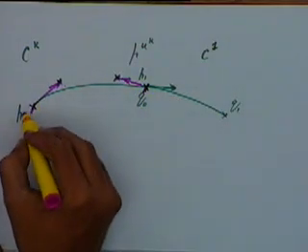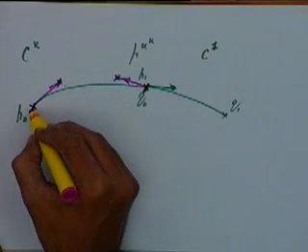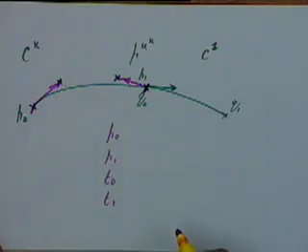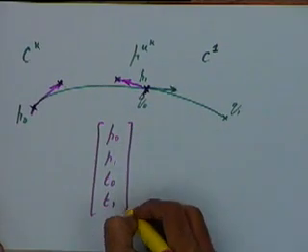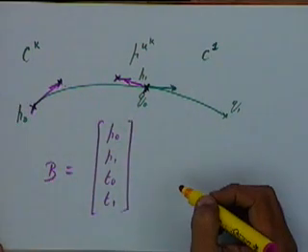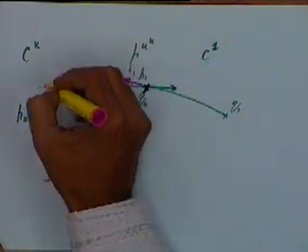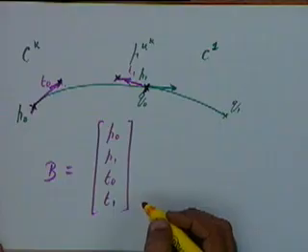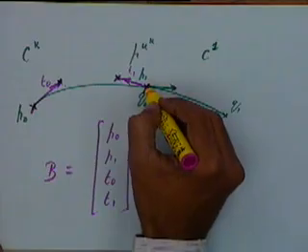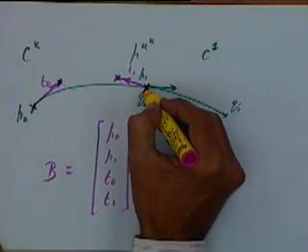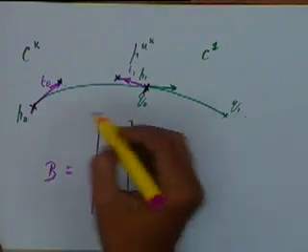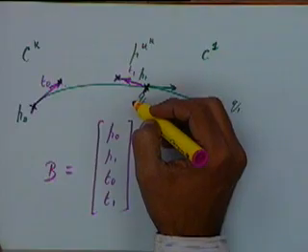If I consider the geometric form of this curve, that will consist of P0, P1, T0 and T1. This is the definition for this first curve, the B matrix for the first curve. This vector is T1, this vector is T0. So, even if I change P0 and T0, my continuity at this point does not get changed. The tangent at this point is given by T1, the end point is P1. So, we need to know that if we have a composite curve, what kind of changes will disturb the continuity and what kind of changes will not disturb the continuity.